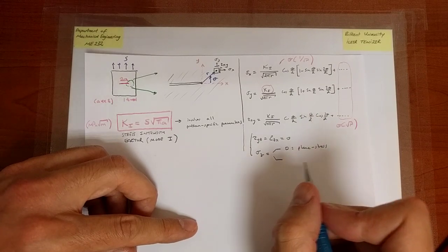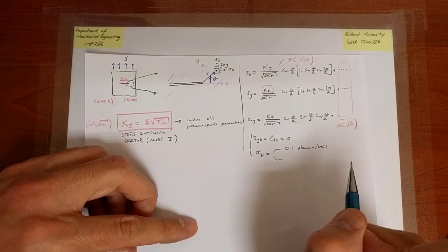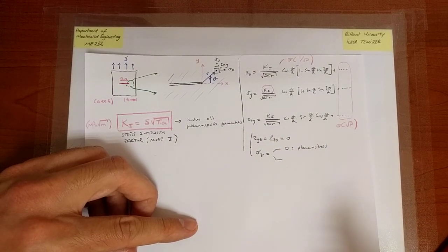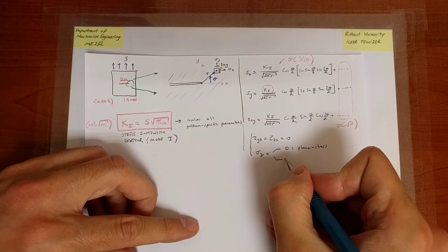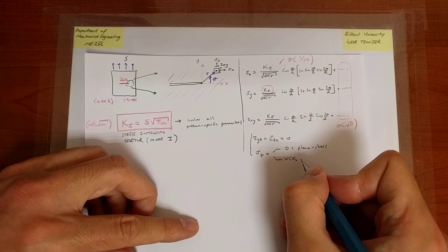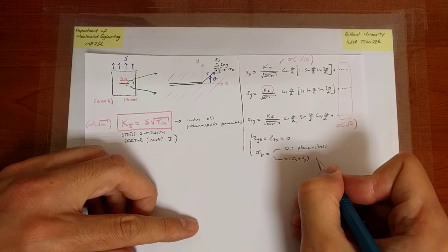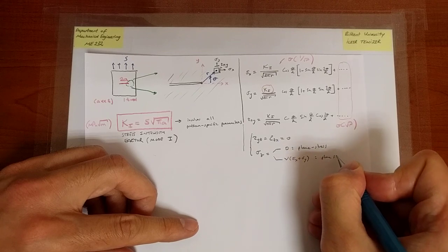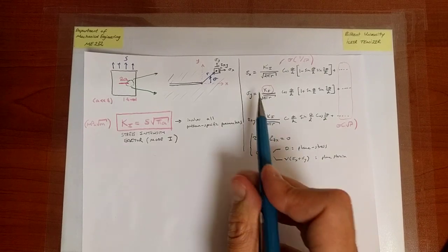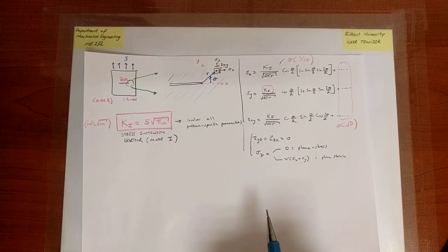But if it's a plane strain problem, remember we are assuming elasticity, and goes without saying, as I've expressed before in the rest of the course, we are using isotropy, and therefore directly from generalized Hooke's law we find that, because it is plane strain and not plane stress, that would be the value of sigma z. So sigma z is something we can post-process from the known stress field.